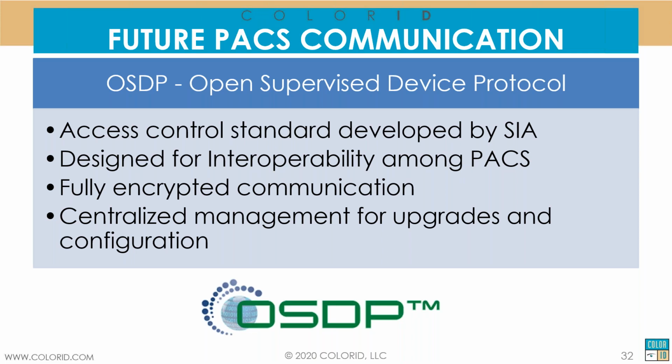And one of those is the Wiegand interface, which is also relatively newly vulnerable. Those are the wires that run from the reader to the panel, and the data's in the clear. The zeros go down one wire and the ones go down the other wire. And the timing is a big deal, but otherwise, there is a little device you can slap on those wires and it will transmit over Bluetooth and tell you what the numbers are, and you can reproduce them. And so with your phone, a little app that works with this device, and that device clipped behind a reader, you can open doors. So that is a vulnerability. There are also other ways that this data is vulnerable.